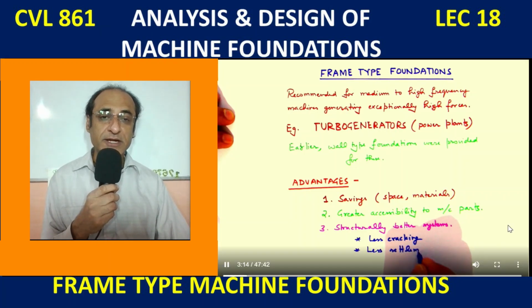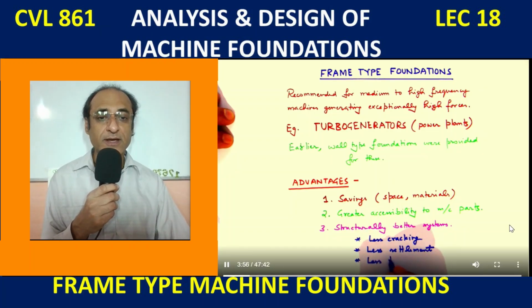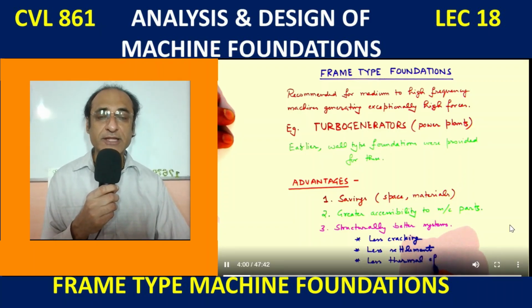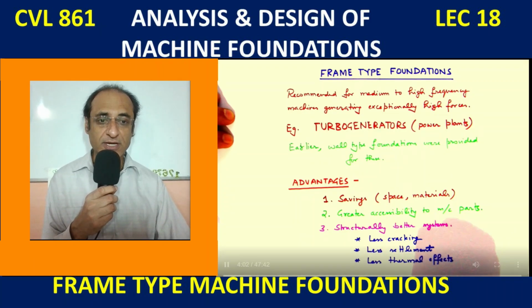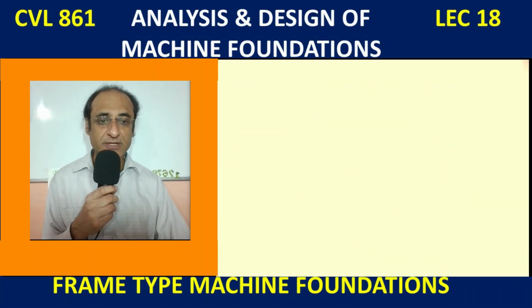And besides that, because we are providing frames and we have a very heavy raft also, they show fewer problems of cracking, fewer settlement issues, and they also don't suffer so much from thermal effects.